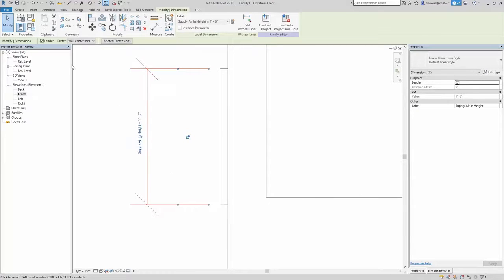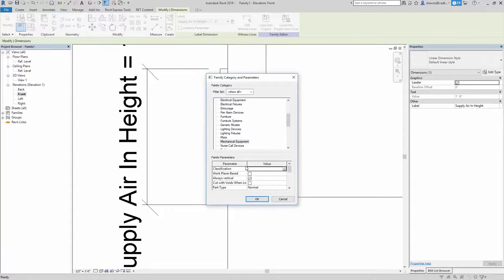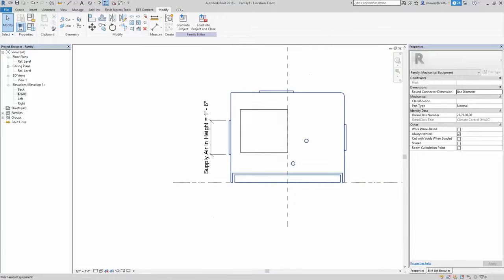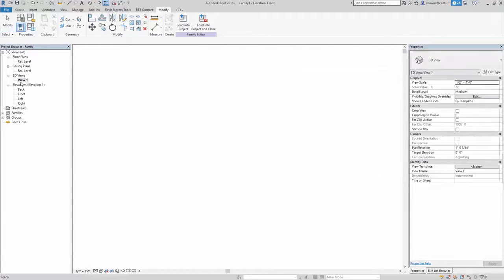Now, because I can't flex this, I'm going to protect this model a little bit from an end user trying to go in here and change these values. I'm just going to set it at least 1.5 feet here and 2 feet here so it locks it down, and that way an end user can't touch this. This isn't a parametric family just because it's a DWG import or an SAT import. It's not that smart. But I do have this other ability here.